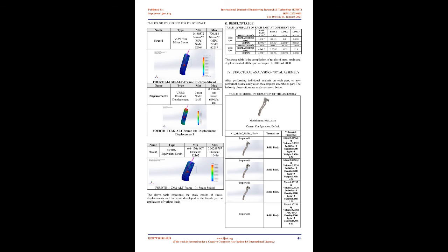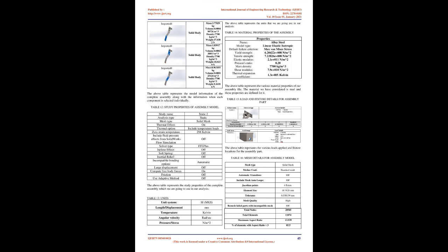The software formulates the equations governing the behavior of every element, taking into consideration its connectivity to other elements. These equations respond to known material properties, restraints, and loads. Next, the program organizes the equations into a large set of simultaneous algebraic equations and solves for the unknowns. For example, in stress analysis, the solver finds the displacements at each node, followed by the program that calculates strains and stresses.